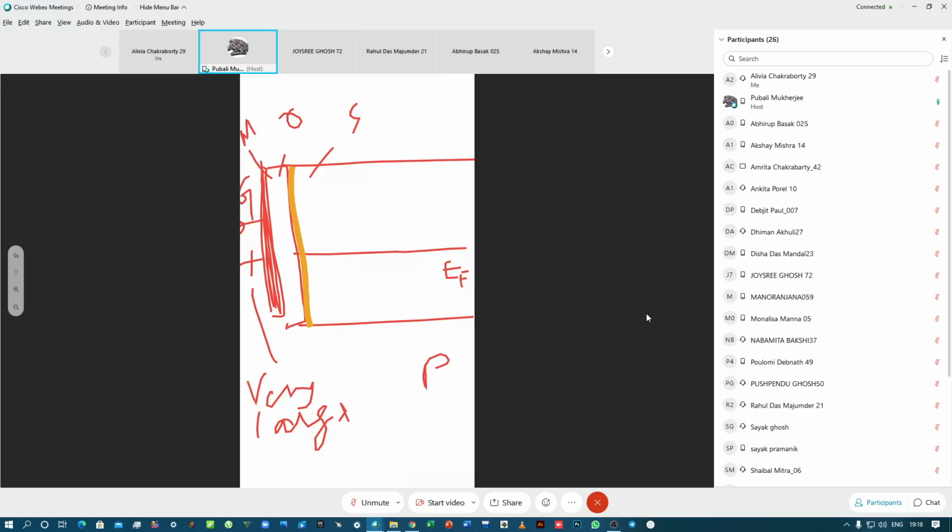Fine. So if there is such high accumulation of charge, then what is going to happen? There will be large number of negative charges accumulating. So at that region, that is the oxide semiconductor interface, the substrate, this P substrate becomes more N type, more N type.